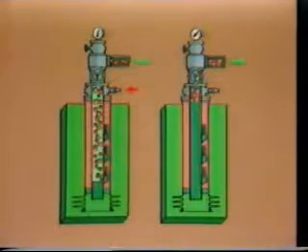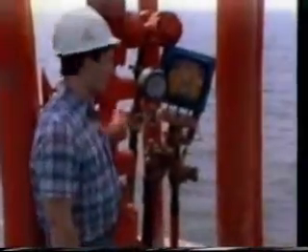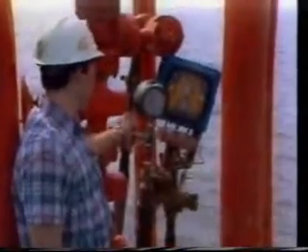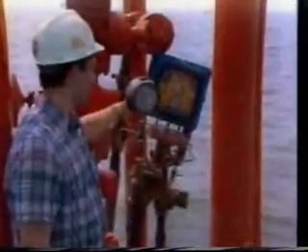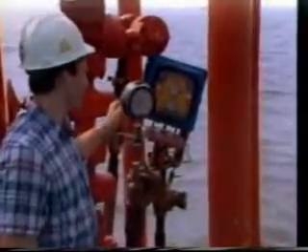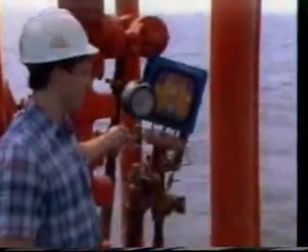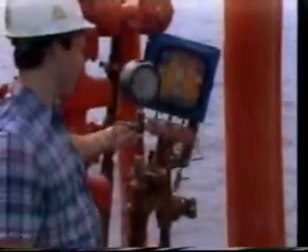Let's go to the Gulf Coast and see an example of a gas lift installation. We have a source of high pressure gas that comes from the compressor station, comes in the line right there. You have an actuated valve with a controller on it. This one happens to be a pressure actuated controller. It allows how often the gas will come in. It just operates the valve, open or close.